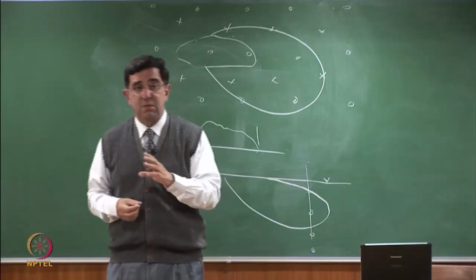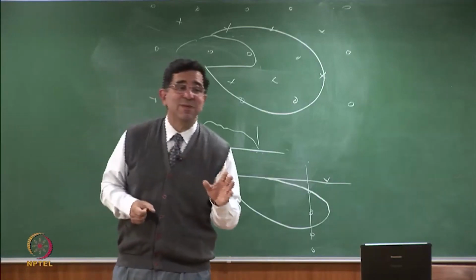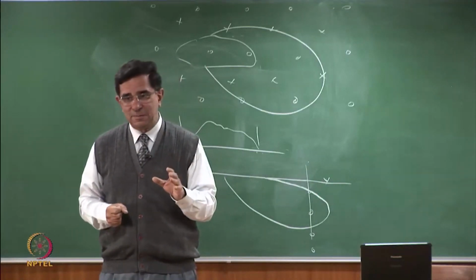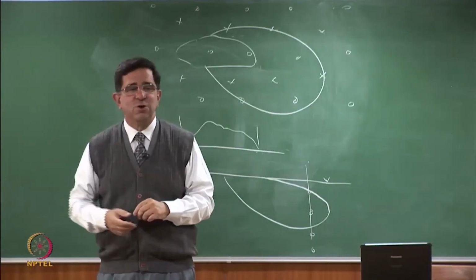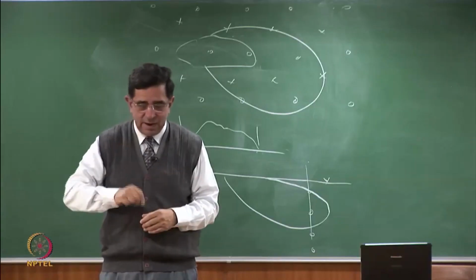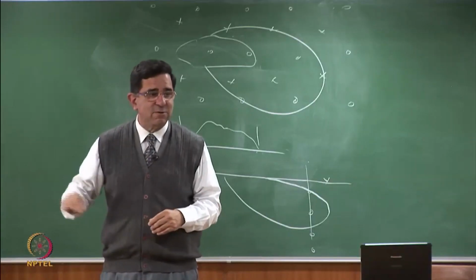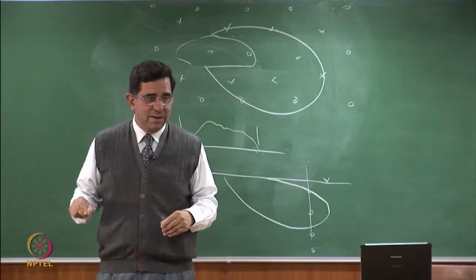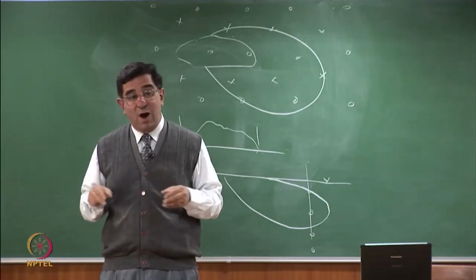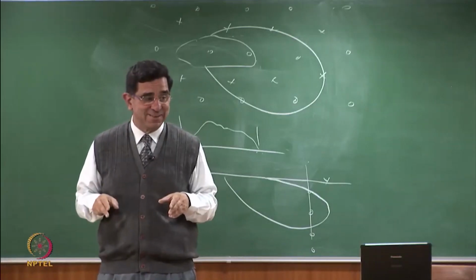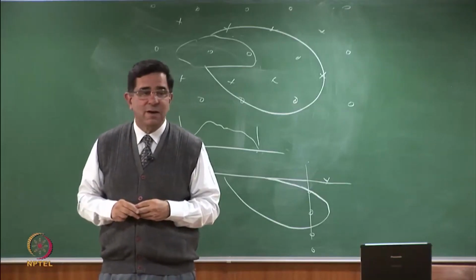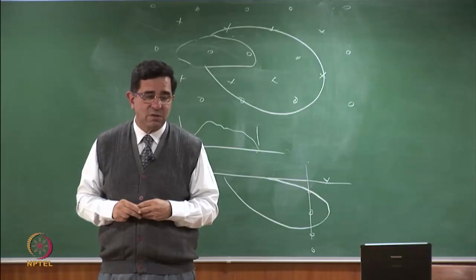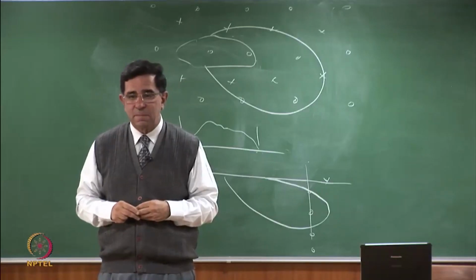It's tough, it's expensive. It's very easy to miss contamination. Please understand. I can go to a site and say, oh, I did 2 boreholes, there was no contamination. Hence, hereby it is certified that the landfill is not leaking. What you have to actually do is to hunt and sniff around for the contamination. And after you have done enough, then say there is no leakage or it is not causing underground contamination.